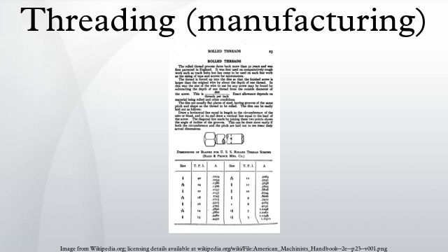Finally, the centerless thread grinding process is used to make headless set screws in a similar method as centerless grinding. The blanks are hopper-fed to the grinding wheels, where the thread is fully formed. Common centerless thread grinding production rates are 60 to 70 pieces per minute for a 0.5 in long set screw.